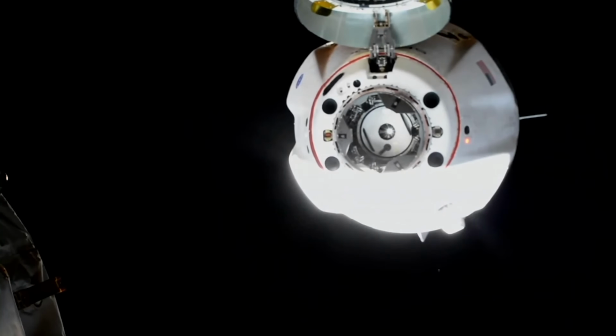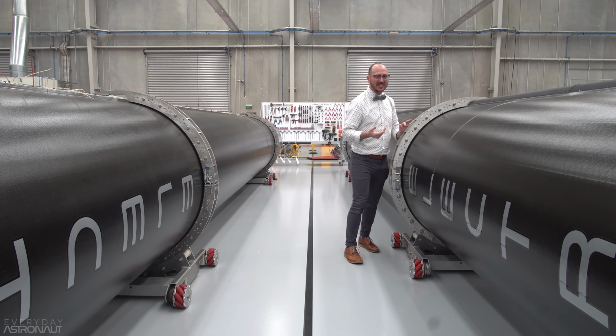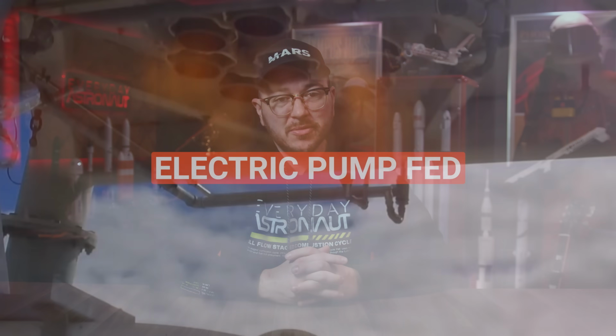Now, despite not being as commonly used on launch vehicles, it's extremely common for reaction control thrusters, and you'll see it used on almost every United States spacecraft, from the Space Shuttle to SpaceX's Crew Dragon capsule to the Apollo Command and Service Module, or even the Gemini capsule. Pressure-fed engines have a big limiting factor, and that's the weight of the tanks increases the higher the pressure in the system is. So what if instead of having high pressure heavy tanks, you used low pressure lightweight tanks and used a pump to shove propellant into the engine? Well, although that can get really complicated, there's one system that's extremely simple.